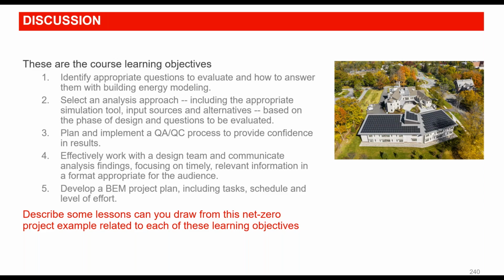Look at the questions. Sean asks, is ERV degradation significant? Sean, it can be. I've seen a case where a particular building was trying to go for net zero, and the installation of the filters around the ERV basically was blocking filter access. And so the filters that were in place were the original filters. They'd been there for over a year because there was no way to get a new filter in or get the old ones out. And they lost about 15 or 20% of the ERV effectiveness there because of increasing static.